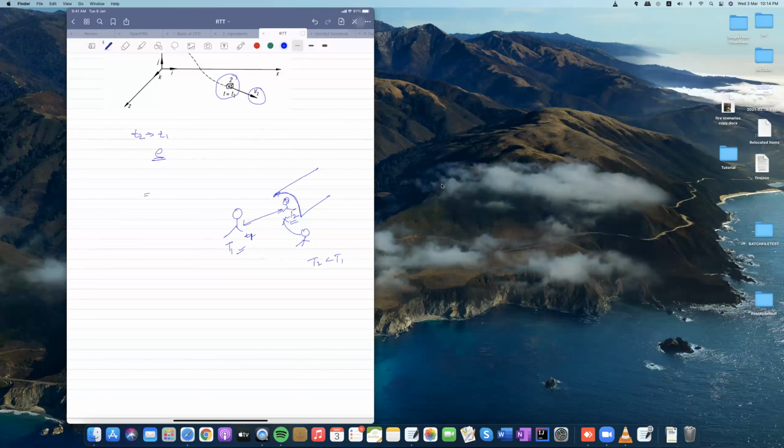So the total change, for example, in temperature would be dT over dt plus the term due to velocity from here to this location. So this total change would be equal to this value. This is the substantial derivative. So this is all in this tutorial, and we will go further and use this when solving the conservation of mass, momentum, and of course the Navier-Stokes equations, which is the heart of CFD.